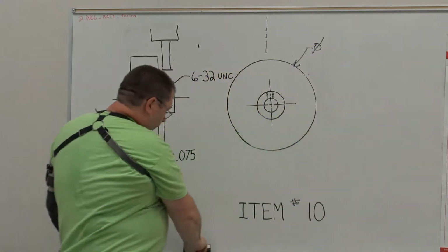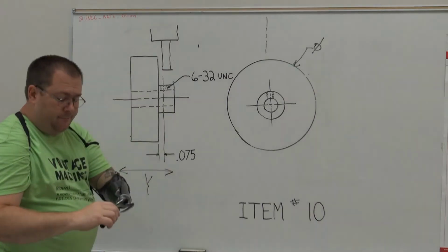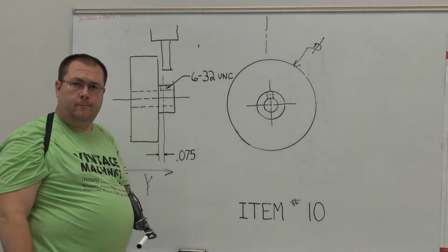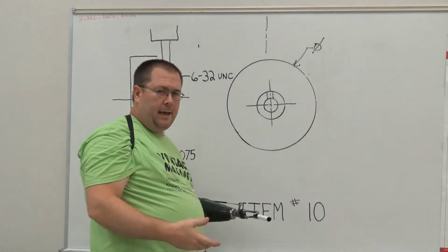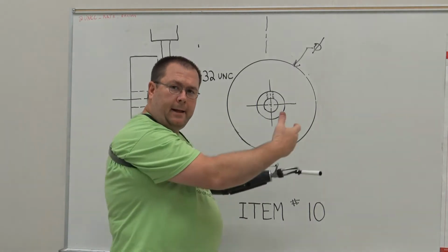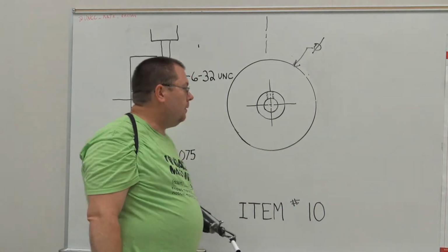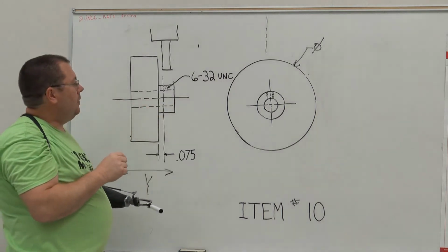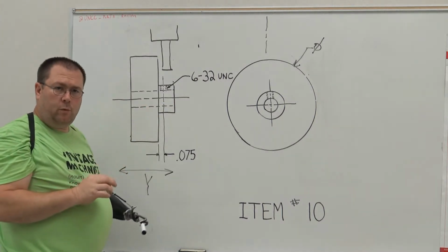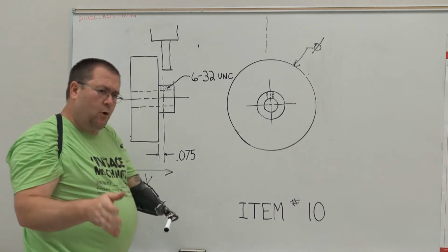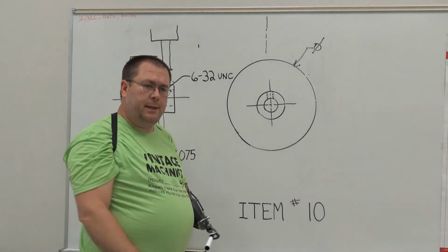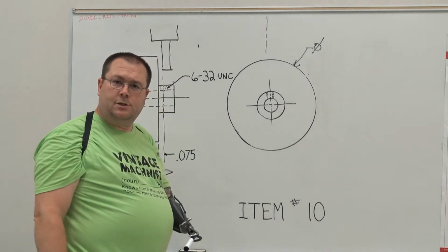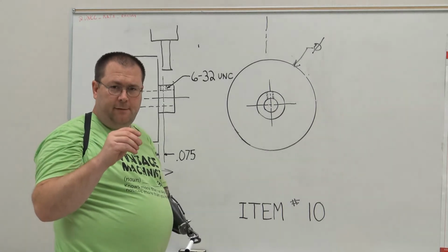is I want to go over step by step how I'm going to put the hole in. There's a couple of calculations or looking at information that we have to do. So now that we're sitting where we need to be, we have to decide what size hole we want to put in. Well, before we drill holes, what do we typically do? We typically do a center drilling operation. Remember, they're short and stiff.